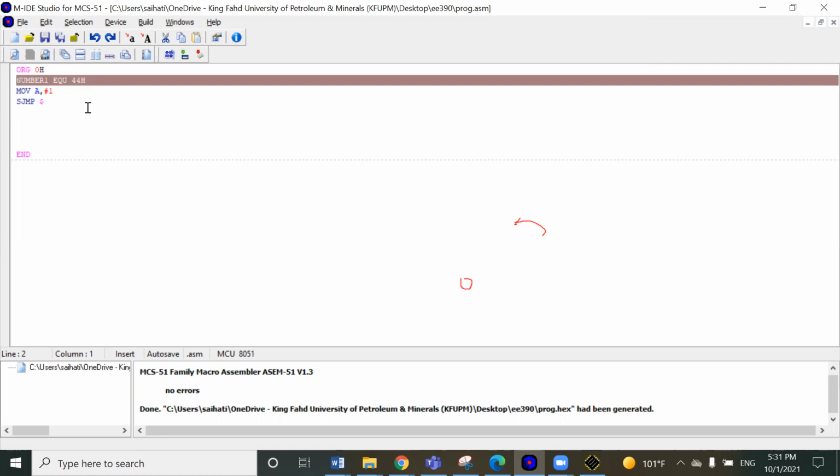I use this like, for example, in Arduino, I can define an integer LED1 to be 3, and in the whole code I can say pin mode LED1 output and then digital write to LED1 high or low. When it is assembled, it will replace all of these with the actual value. There is nothing called LED1 after conversion. It's the same thing.